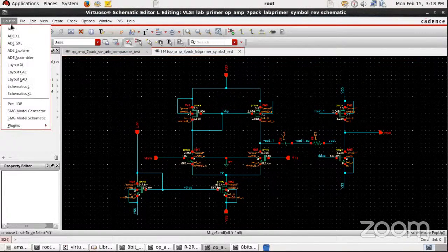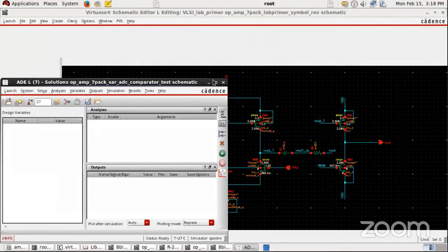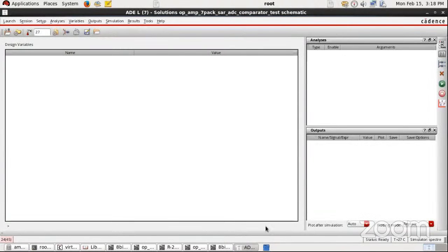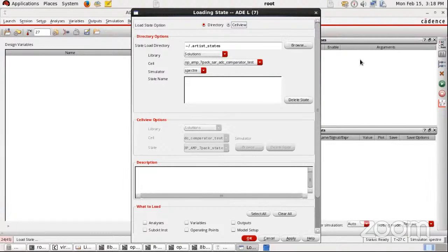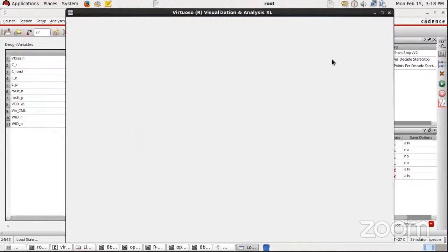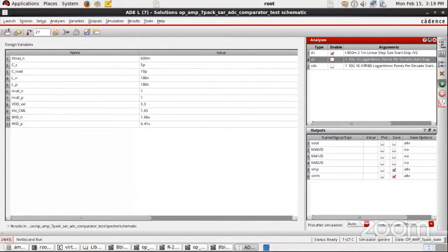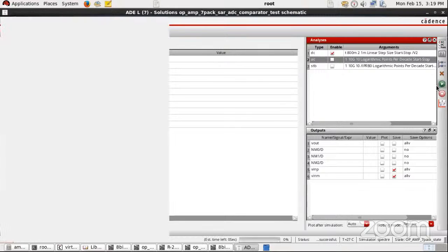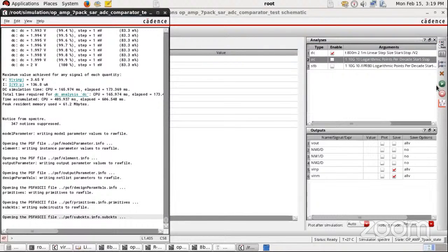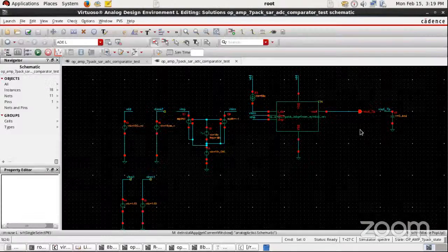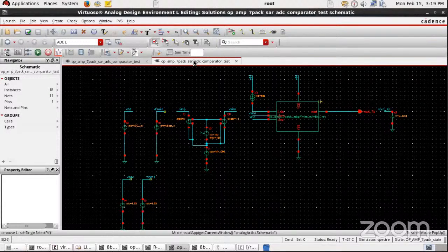So you should also make sure, based on the circuit or devices that you have made use of in order to build a block. For example, if you have made use of MOSFET, then you should make sure that all the devices are in saturation. So I'm just running a DC operating point analysis alone, because I am going to check whether my transistors are in saturation or not. So to check that, I'll just run a DC operating point analysis, and I'll go back over here.